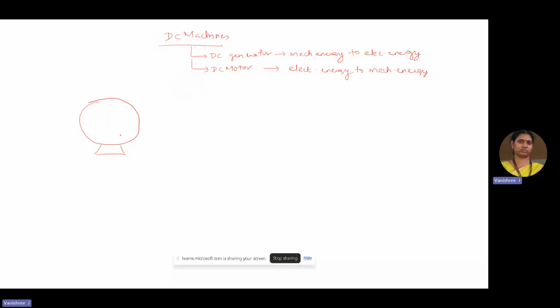It provides the mechanical support to the machine, and it also holds the field poles to which the field windings are wound. We know very clearly, if there is a north pole, obviously there will be a south pole. So poles occur in pairs, so the number of poles will always be even in number. Just for a sample, a two pole machine has been shown here, and this outermost covering is called the yoke.